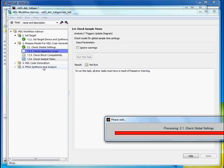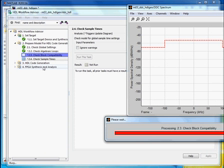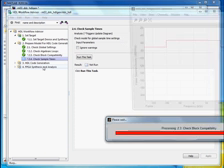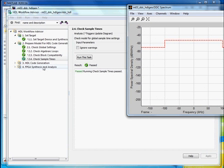So we can run these task by task, or we can go ahead and say run through a given task. So now what we're doing is checking the overall settings to make sure they're ready for HDL code generation, making sure all the blocks in the model are compatible with code generation, and getting generally prepared for that code generation process. Okay, so now we're all set, and let's look at the code generation options here.